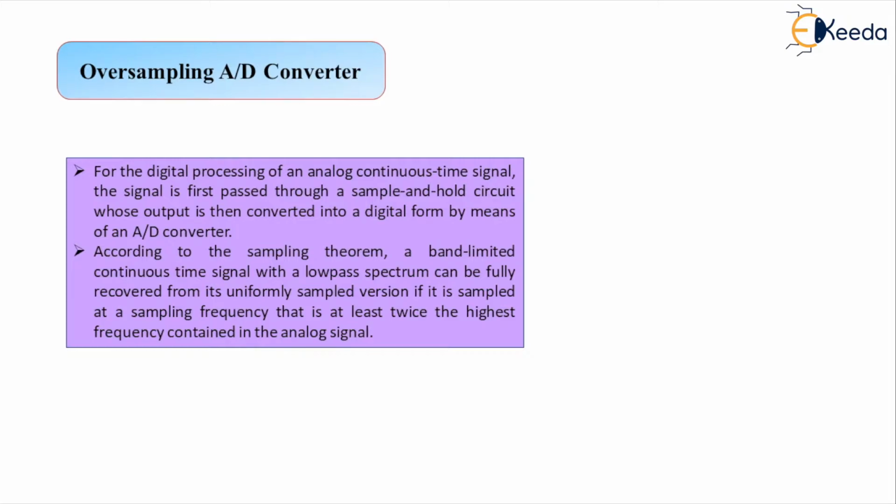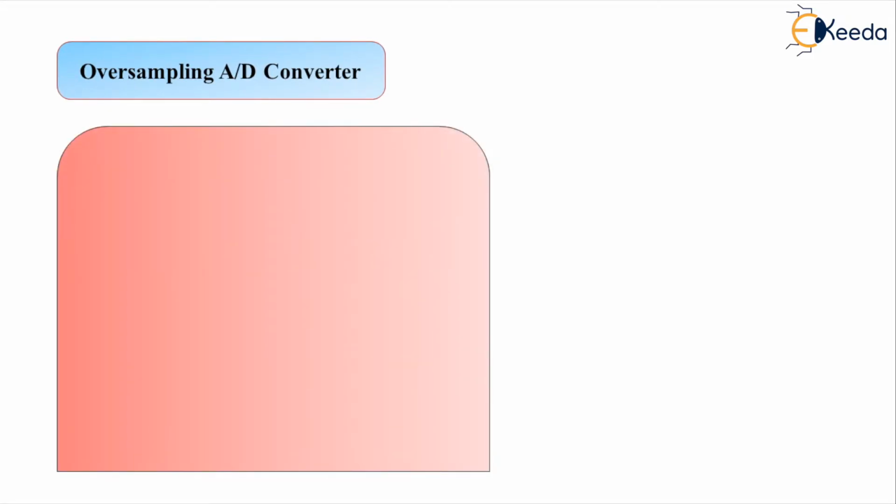Now the passband cutoff frequency of the low pass filter is selected to be equal to the frequency of the highest signal frequency component that needs to be preserved at the output. The anti-aliasing filter also cuts off all the out of band signal components and any high frequency noise that may be present in the original analog signal, which otherwise would alias into the baseband after sampling, and the filtered signal is further sampled at a rate that is at least twice the cutoff frequency.